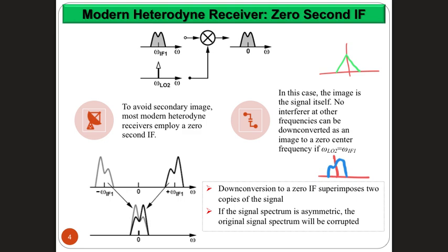No, it does. The phase difference, right? That's the trick, yeah. So the trick is when you have a combined signal carried over a sine and a cosine carrier, and you add them together, this gives you a complex signal in the time domain, which means you will end up with a frequency domain that is not symmetric. So in reality, what do we do in our transceivers? Typically, we have the signal coming, and then we split the signal into two paths, and then we multiply one with a cosine carrier, we multiply the other with a sine carrier, so it becomes two signals, one carried over an in-phase component, and the other one carried over a quadrature component, and then we add them together and we send them over the air, right?